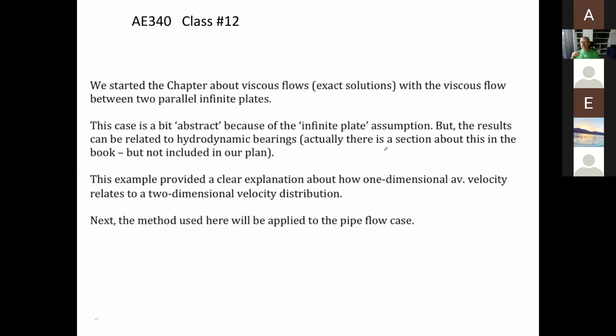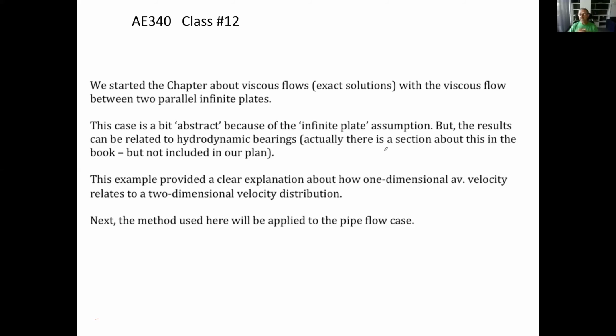So that was because that was really more two-dimensional. The hydrodynamic bearing in your car is cylindrical. So we have to do the same thing in cylindrical coordinates. On the other hand, in the book also, there are the two concentric cylinders, which you can look at as well. So it will give you what kind of torque you need to rotate two cylinders, one inside the other, if you fill it with so much liquid, and that's the spacing and so on. So it has some scientific information about designing bearings. But again, this is just a side remark.